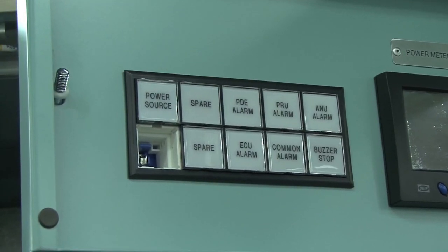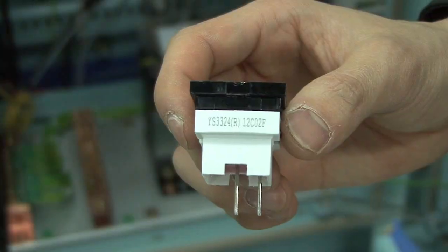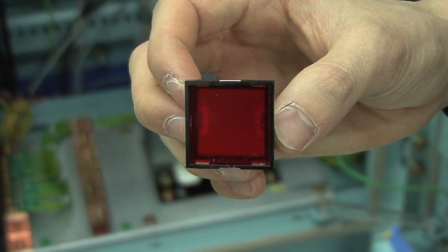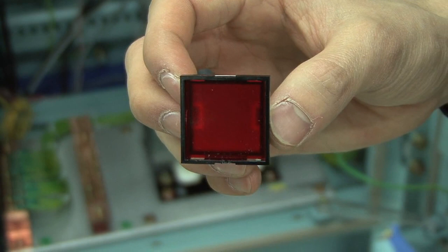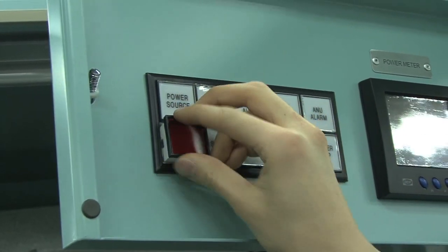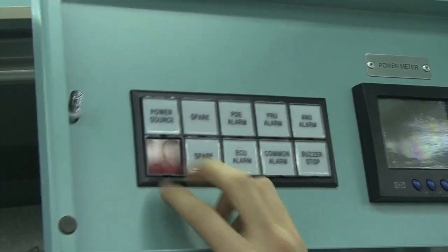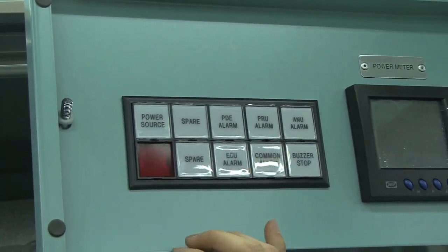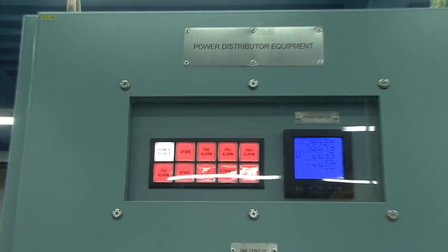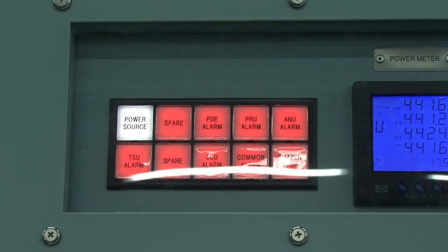Indication lamp. Applicable equipment and location, PDE. Step 1. Disassemble lamp part and acryl cover with a screwdriver. Step 2. Remove lamp from the lamp part with a screwdriver. Step 3. Check socket and voltages of a new lamp and reassemble the lamp, following instructions in reverse order from Step 2 to Step 1. Step 4. After the power is on, check the operation state using lamp test switch.